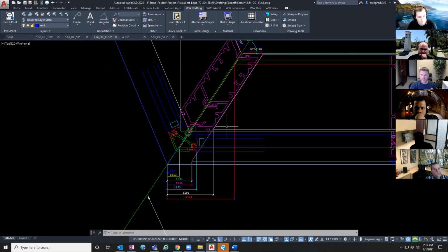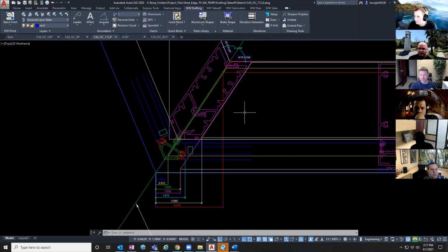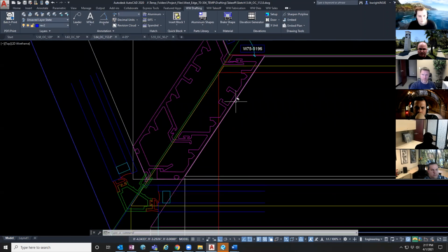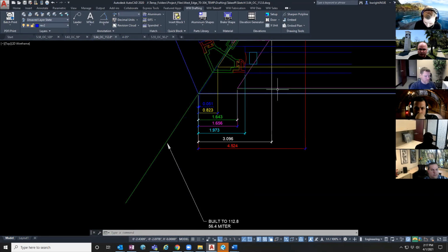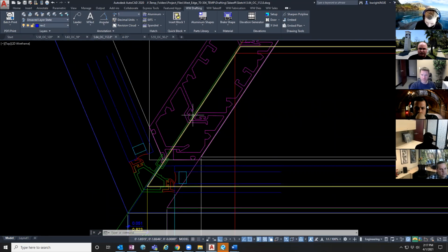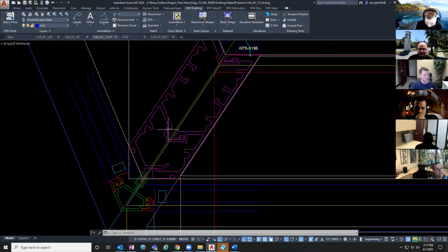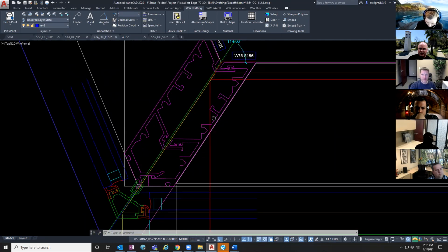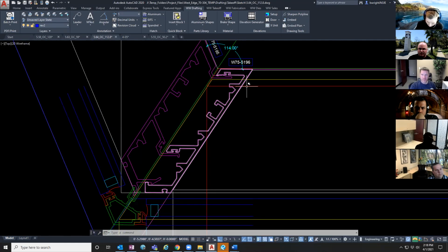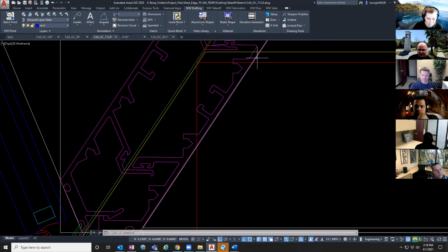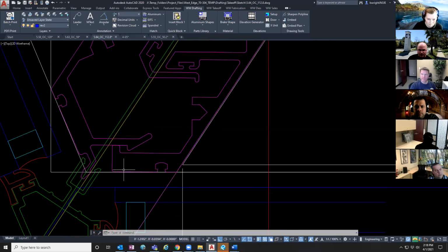The preferred method is similar to some of the layouts we did on South Main, where if we had this 114-degree mullion pair, but we needed it to work for this 112.8, we would have laid out the 112.8 on the floor plan layout and then rotated these mullions so that they would stay parallel to the glass pocket.